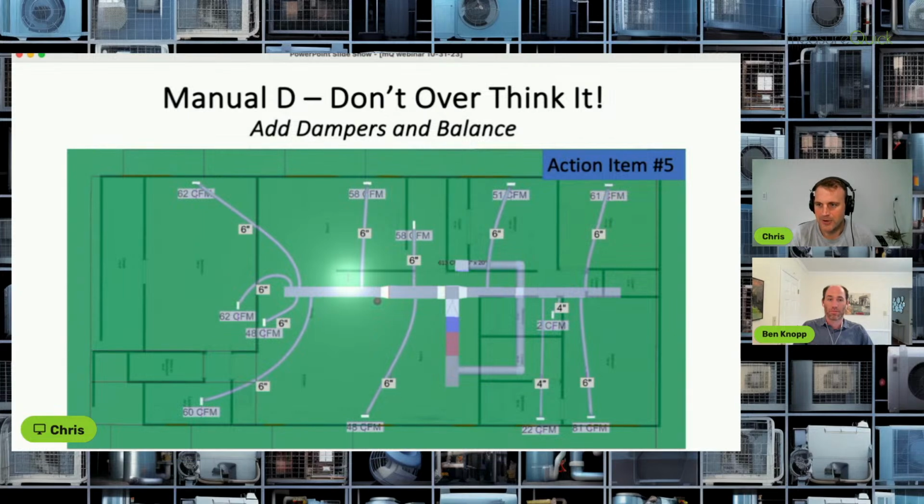So when I went there and there was a 3-ton, I ran a TrueFlow report on this existing system. You'll see it has a massive amount of square trunk line underneath the house, right? And I don't know anything about the job. I get there, the system's sitting on a floor on a couple bricks. It's a terrible looking install. And there was an electronic air cleaner right next to the back of the blower. And duct leakage was super bad. We were talking way over 400, right?